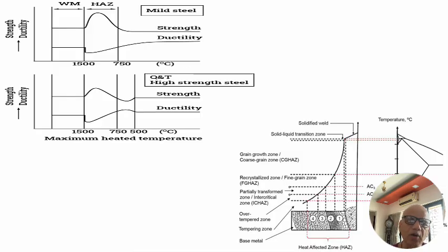you are taking care of your weld as it is shown here. The parent metal is already taken care of; we have taken the graded material, tested material, so this side is not really a worry for a welding engineer, because that's the job of the planners, the procurement agencies, the QC to give us the right material for doing the equipment and joining it. We select a good consumable, so the welding engineer's first job is taken care of. He selects the right parameters by which we will be able to weld it properly.